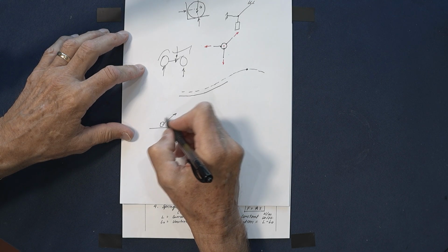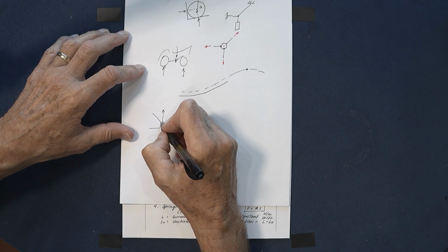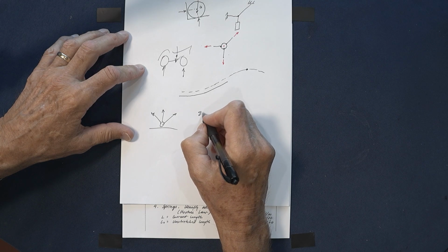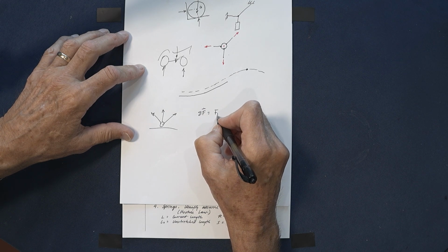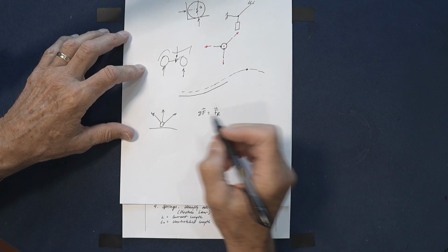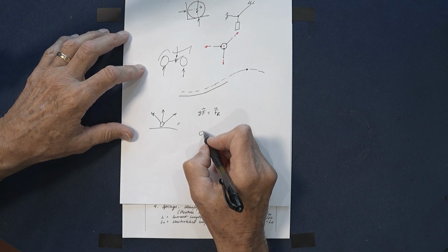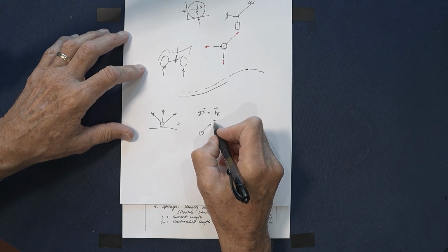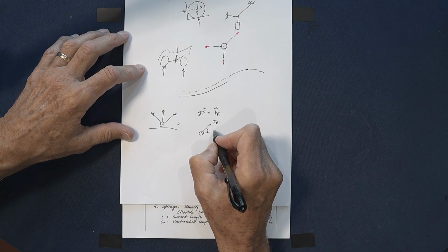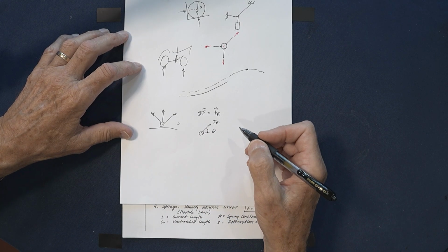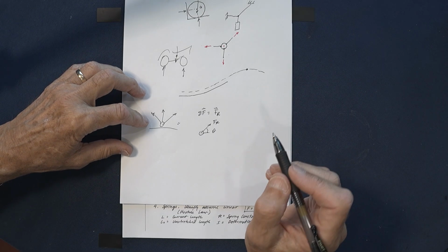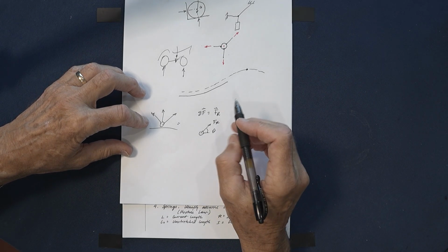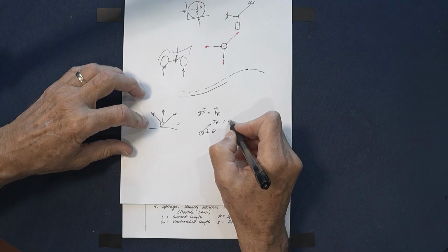And we had several forces acting on that ring, and we would sum those forces to some resultant. We would replace this with a single resultant force acting at some angle. That's a resultant problem. But for equilibrium to occur, this resultant has to be 0.